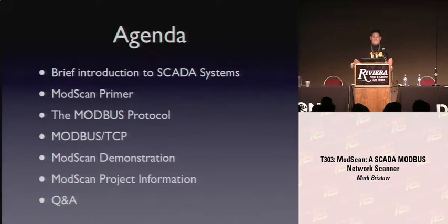Then Modbus TCP, which honestly is just a wrapper for Modbus into TCP, although they changed the packet structure and the protocol a little bit. So I'm going to go over that architecture, packet construction, and then we're going to look at some packet captures. Conveniently, Wireshark actually decodes the Modbus protocol, so that's kind of nice. Then we're going to get into the demo.